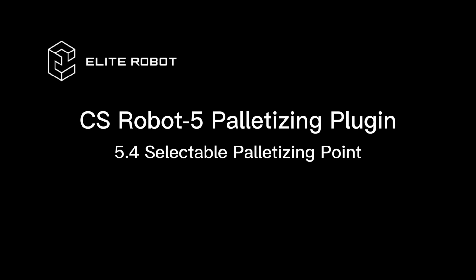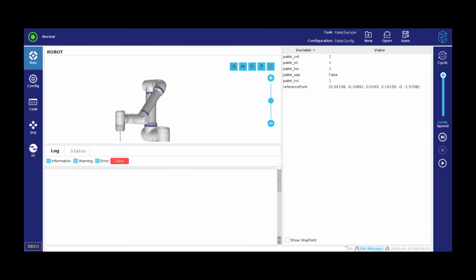Section 4. Selectable palletizing point. In real palletizing applications, sometimes there will be a fault, causing the task to pause or stop. After the fault is cleared, depending on the situation, the user might need the palletizing task to start from a specified palletizing point. Therefore, an interface to specify the palletizing point needs to be added.